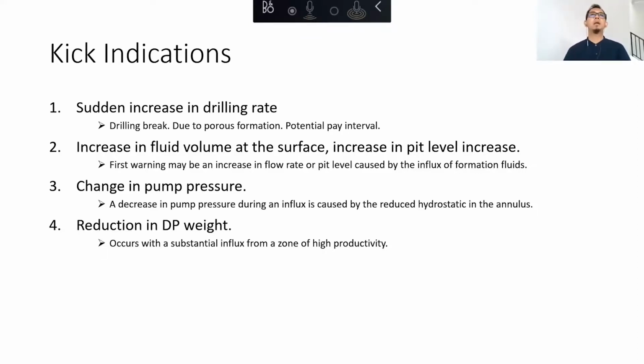And then up in the air without a hydrostatic column, the weight might be 1.5 million pounds. But when you put it into the hydrostatic column, it gets lighter. Maybe it only translates to 1.1 million pounds. But in the end, you don't drill with 1.1 million. You don't fully lay the drill pipe and the bit into the formation with 1.1 million of weight. You put only maybe 500,000, maybe 400,000 pounds.